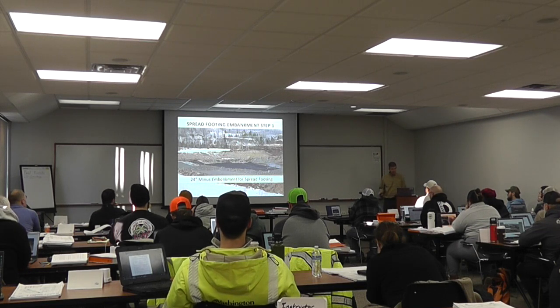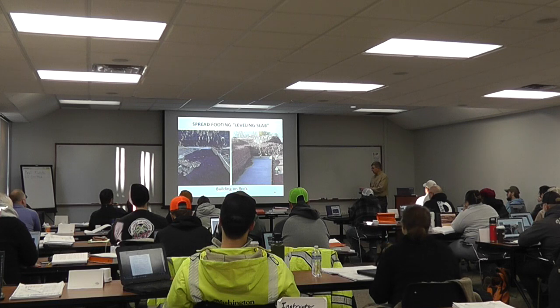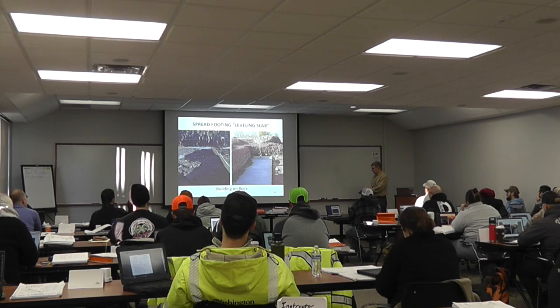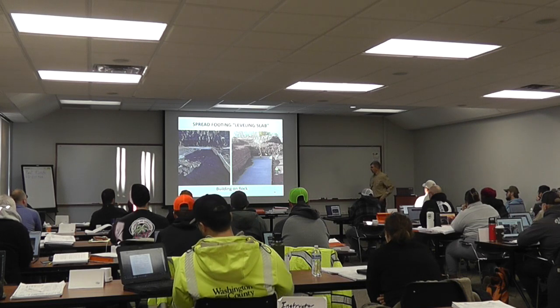So here's some 24-inch minus embankment for a spread footing. In this case there was also some bedrock, but we see it's kind of on a slip plane, we might say. The bridge is off to the right, and so they filled with a fill here and then cast the footing on top of that.